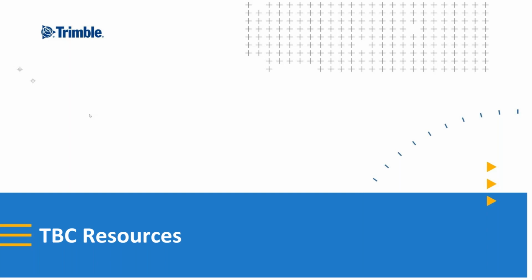Where you may normally have, let's say, 2 or 3 lanes that deviate from the center line, your cross slopes would normally be calculated in the corridor perpendicular to the alignment, not necessarily perpendicular to the previous lane edge. Whereas in vertical design, it's calculating to the previous lane edge, which is actually giving you a better cross slope model than the traditional road design method, but it may not match the traditional method. So you just have to be aware of that. But for a lot of roads where there are slope changes, you can certainly handle that with the vertical design tool.